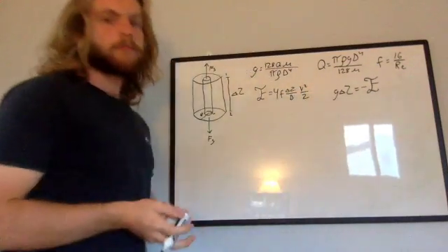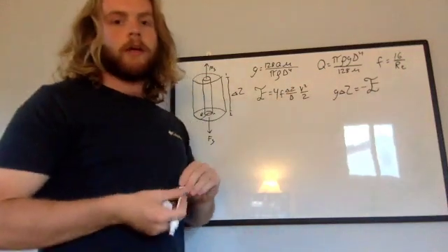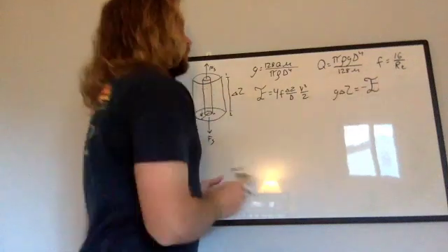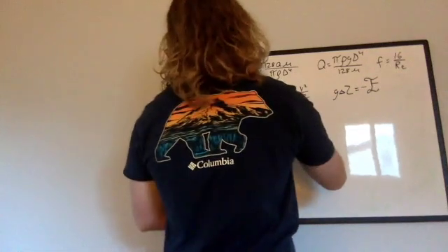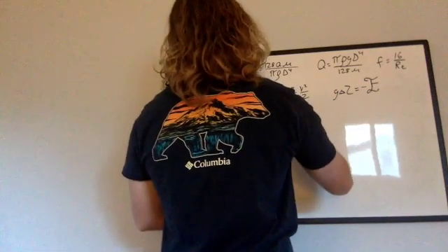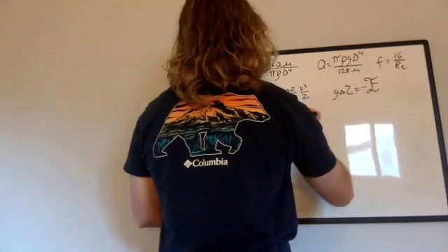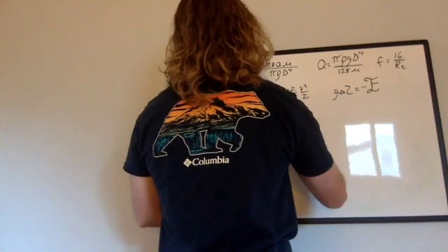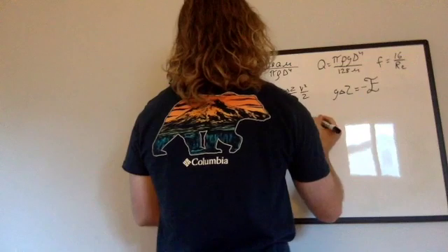All right, so this is our expression for our frictional heating right here, and we can substitute this in over here, and substitute in our G at the same time. So we're going to get 128 Q mu, bring our delta Z in, over pi density diameter to the fourth.